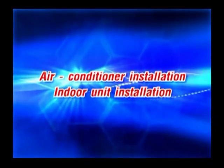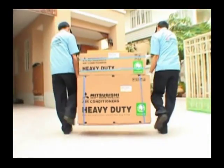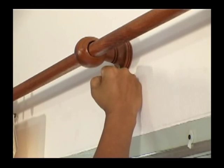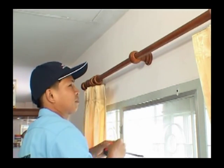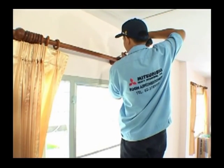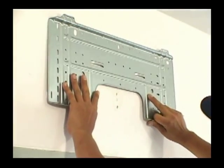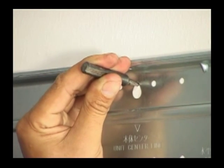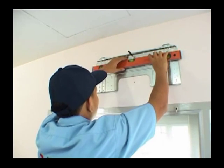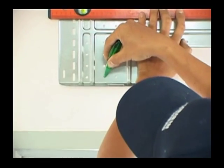Air conditioner installation. It begins with installing the indoor unit. Make sure that the wall where it will be installed is strong enough. Then mark the center of the installation plate on the wall with a center punch. Apply a spirit level and a pencil to determine a level position for the unit.